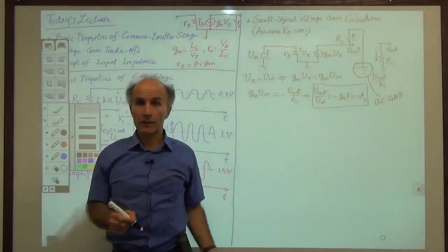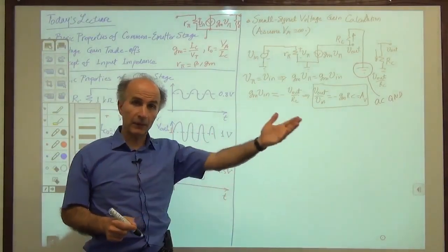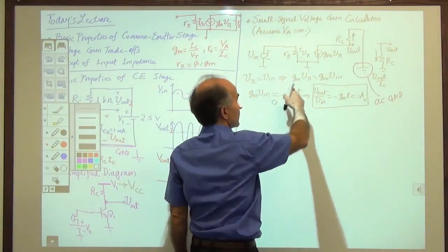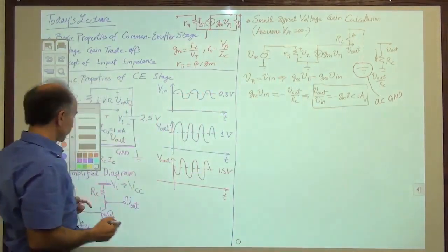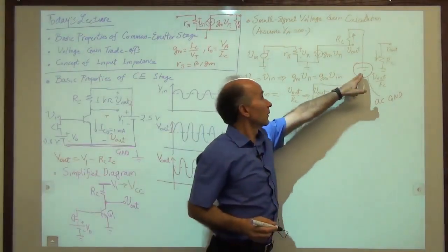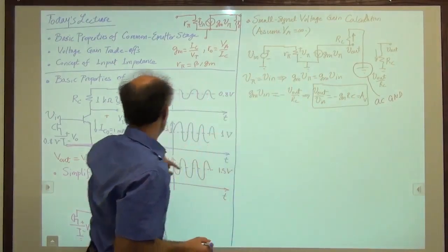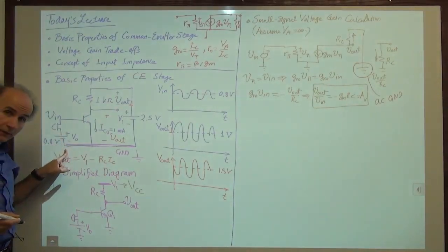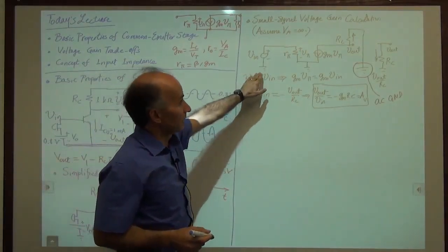Okay? So in a small signal model, we have only grounds, and they're all AC grounds, but some of them came from different places, right? So this is still AC ground, this is also AC ground, except that this ground originally was a ground, as you can see here, but that ground was not. Similarly here, this is also an AC ground because originally the bottom terminal of the microphone was not connected to ground. But because this battery was forced to go to zero, we ended up with a ground here as well.